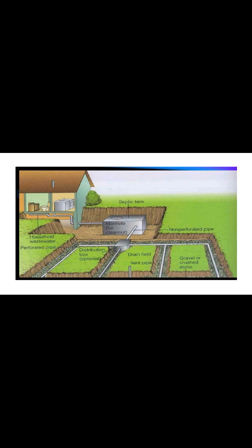The tank is generally of rectangular shape, having a roof. Normally it has two chambers separated from each other by a baffle wall. The first chamber, in which sewage first enters, is called the grit or screen chamber, and the other is called the anaerobic chamber.